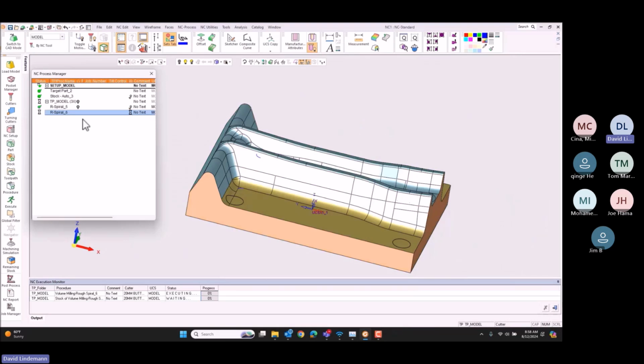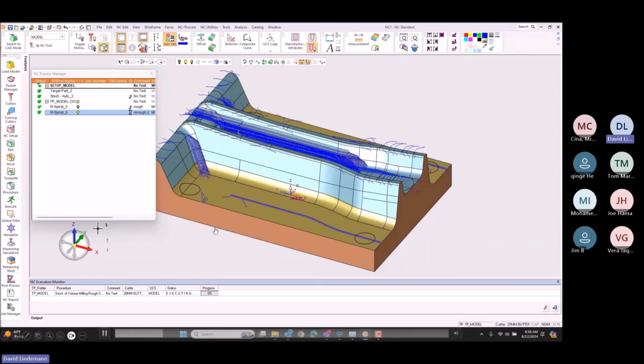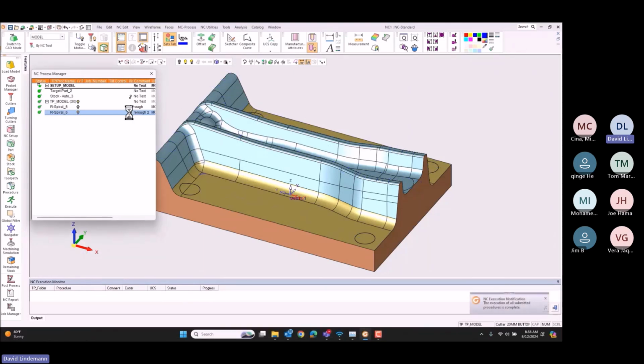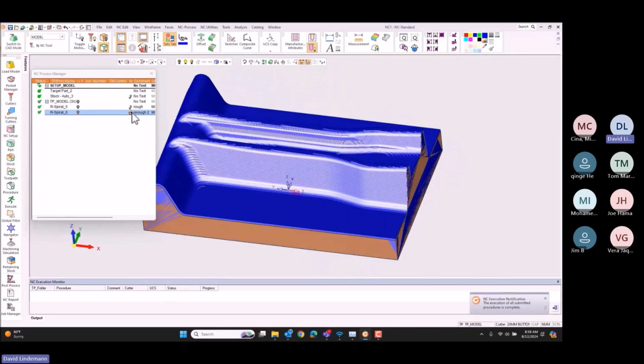And now we calculate. So you can see I'm working quickly because I'm really trying to cram everything in here. But you can see that a lot of times I can just take the previous tool path, cut and paste it, change a couple parameters, and keep right on going. All of this will have greater meaning too, as we go further along, okay? Because again, like I said, I'm teaching us the system the way I want to cut.